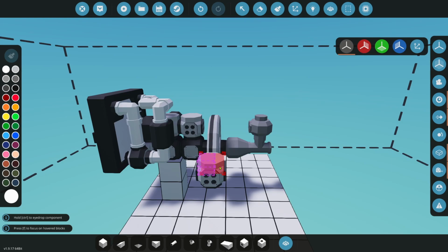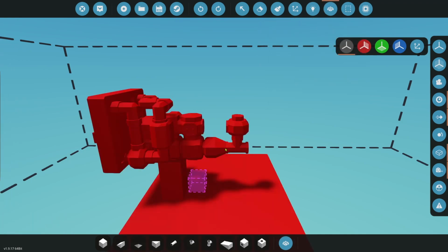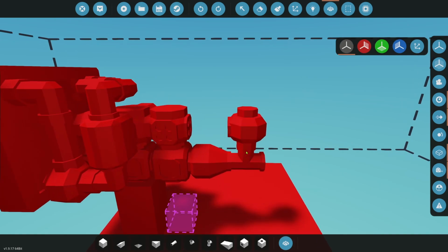This is not good for a race car, but big flywheels are often on things like tractor trailers. They're on things like trains or generation systems for diesel electric trains. They would be on boats to help keep the propellers moving. They're less likely to have shocks in the system. Now, we're just not going to bother with the flywheel now. We don't need it. But keep that in mind. It's going to take you longer to start because that object at rest wants to stay at rest. It doesn't want to start moving. And it's going to take you longer to get the engine to slow down because that object in motion wants to continue to stay in motion. All right, so keep that in mind.